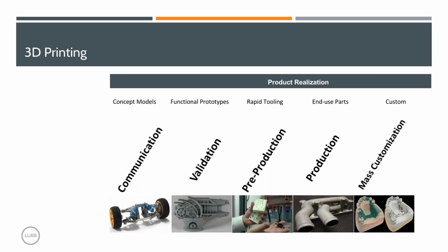They say, wow, that printer is great and everything, but my product has to be specifically in this plastic material because it requires X mechanical properties. And then our answer before was, well, we have this material that's polypropylene-like or ABS-like, etc. Now you can get exactly the mechanical properties that you want. So therefore, the process in that situation would be 3D printing a mold and then injection molding it with the exact material that you want.